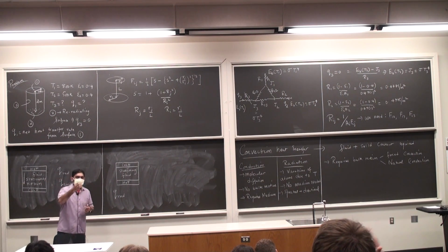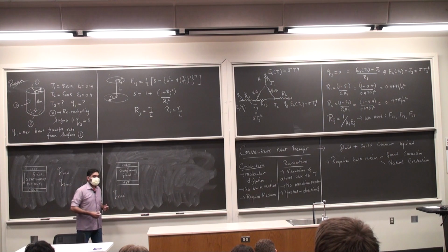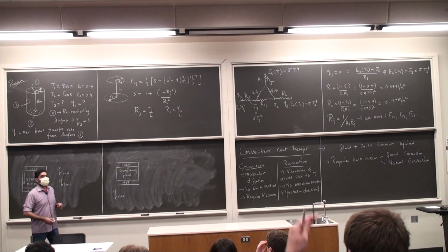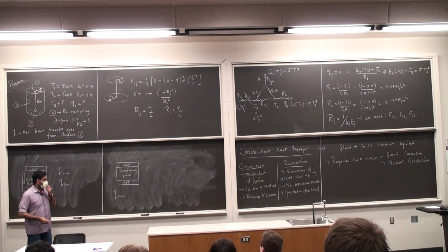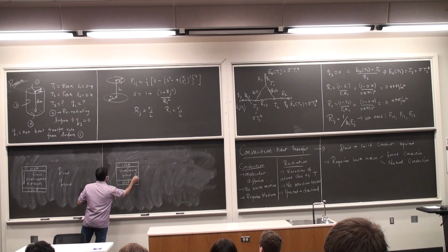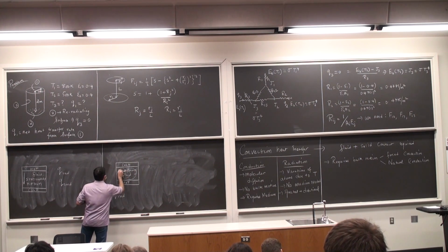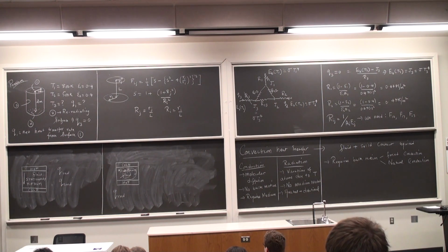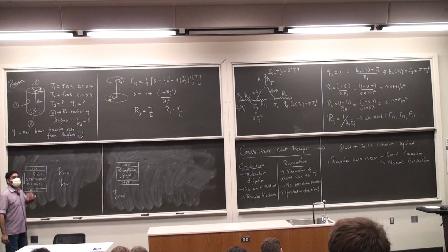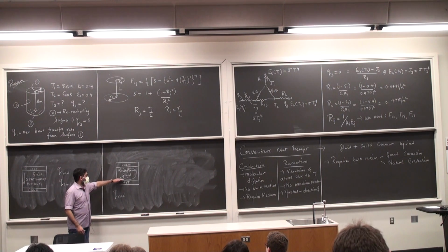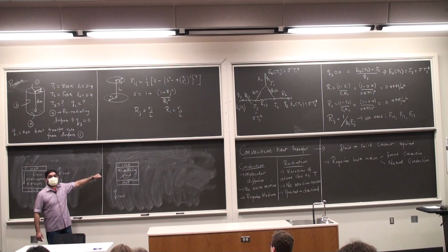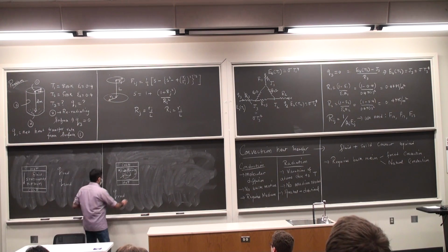Why? Yes? As the bottom surface is heated, its density becomes lesser than that on top. Absolutely, fantastic. So there is going to be a bulk motion created, even though there is no forcing of the bulk motion. There is bulk motion due to natural consequences, because the fluid molecules here get heated up, they become lighter, so they start going up to the top, displacing the heavier ones on the top which come to the bottom, and so this creates a convective current. So there is convection here.